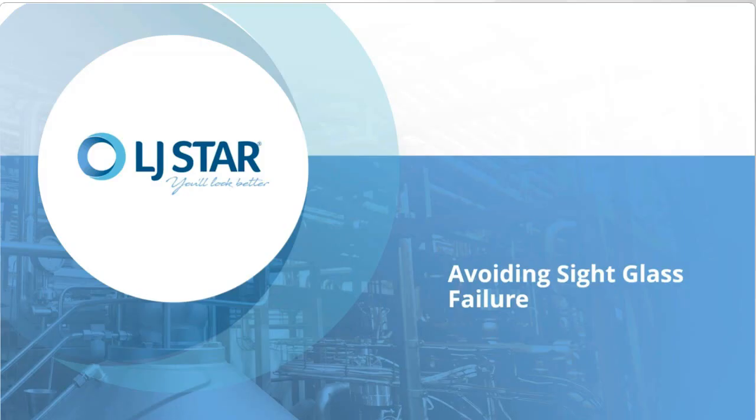What are the ways sight glasses can fail? Sight glasses can fail in multiple modes. They can become cloudy, obscuring vision. They can crack and even leak, putting a batch of costly media at risk of being scrapped. In pressurized applications, they can fail catastrophically, which, although rare, has been known to injure or even kill workers. What are the factors that contribute to sight glass failures?